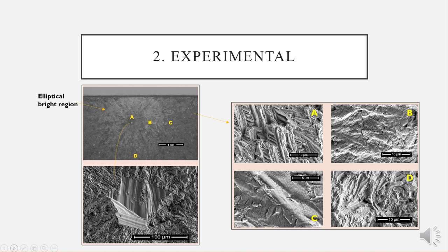As we move outwards from the defect, we observe four different regions in the fracture surface. The first few hundred microns show a microstructurally textured region that clearly follows the typical acicular martensitic texture of a titanium alloy, as shown in the figure labeled A.